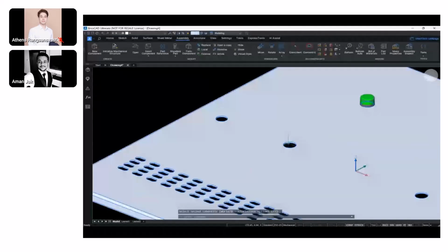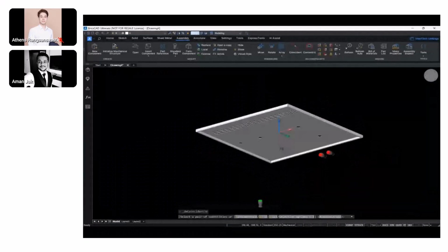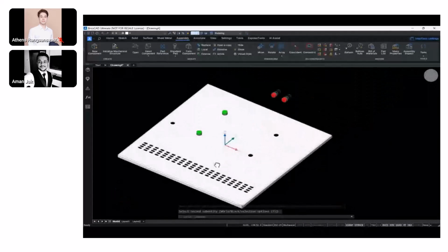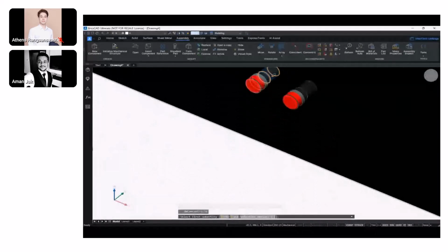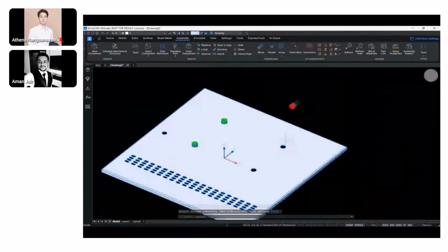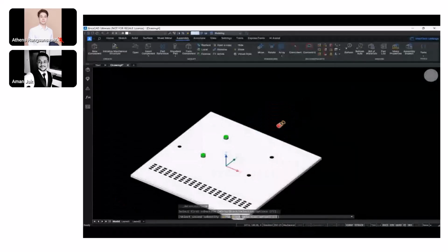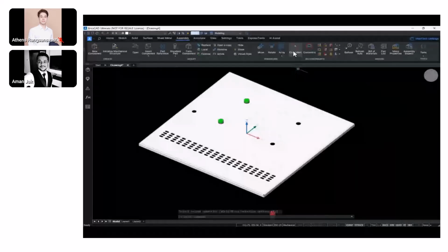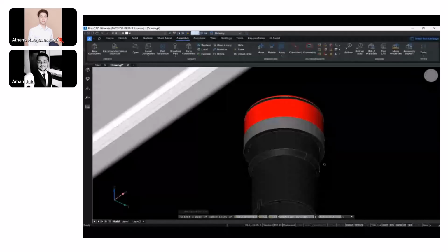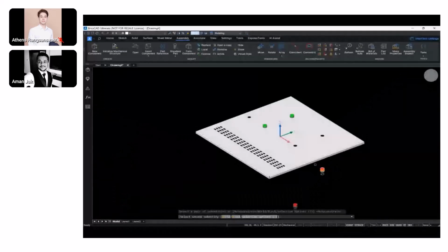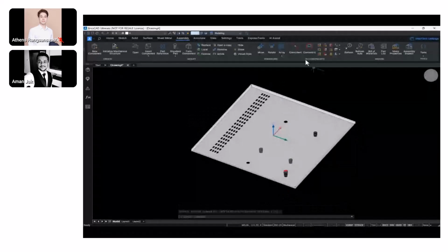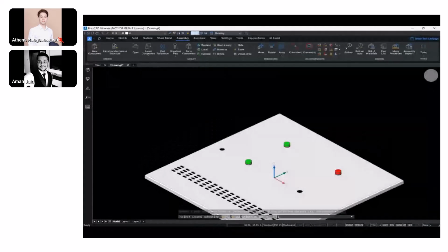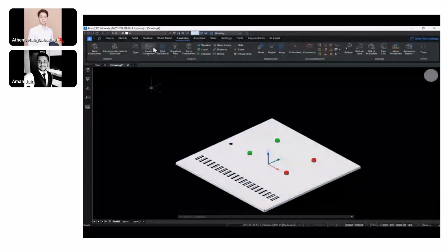One thing that I can do is copy the same switch that I had constrained earlier. Just copy it and place it onto the next hole representation. That would have done things for me. But this is how I can make sure that the constraints that I've applied are perfect. In case I want to change the constraints in the near future, or if the whole geometry shifts, the entire geometry along with the switches needs to shift as well. So if there's a change in the design principles, let's say the hole has to shift by another 10 mm or so, all I need to do is just shift the hole by another distance of 10 mm, and the entire geometry would update automatically, right? So instead of copying it at that particular place, constraining the geometry is really handy. And as you can see, it's really very simple to apply constraints: coincident, concentric, distance, and there are other constraints as well, which help us complete our assembly modeling.